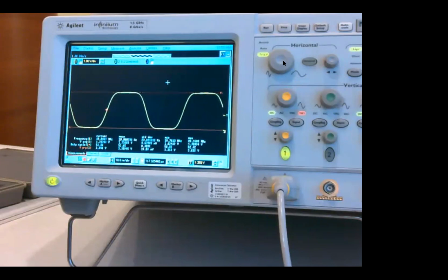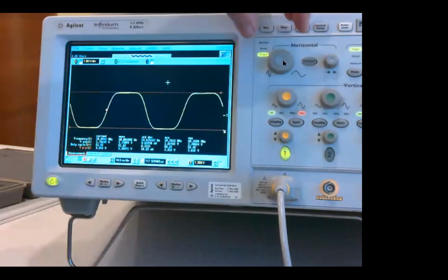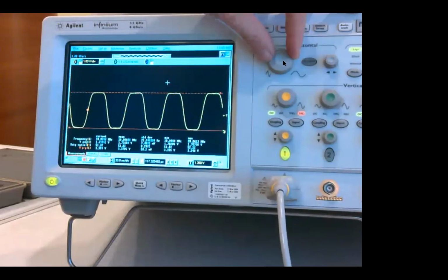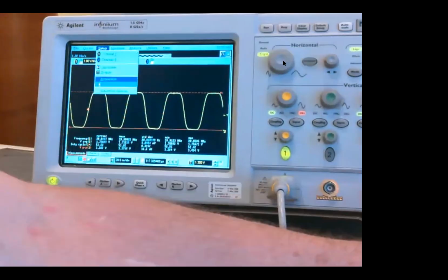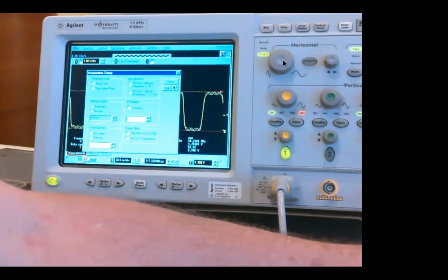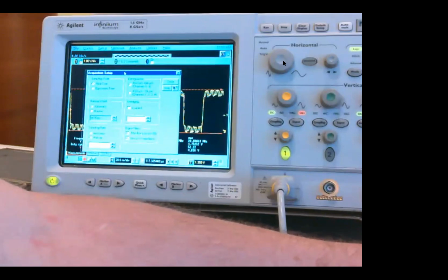Now there is a comment in the thread about Gibbs ringing. So when you slow the bandwidth, you are not seeing too much Gibbs ringing as an artifact of measurement. Not real, but an artifact that confuses your eyes. Okay, thank you. Yeah, interesting. Thanks for pointing that out.